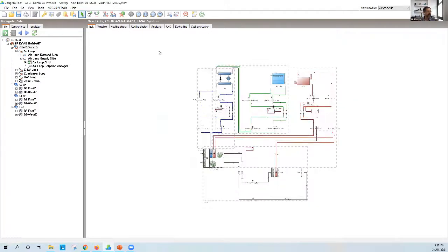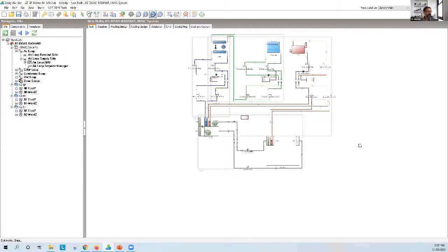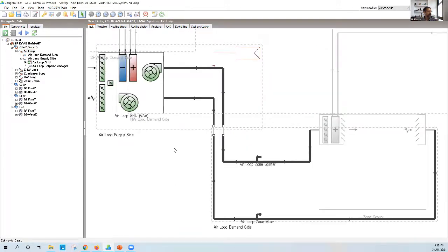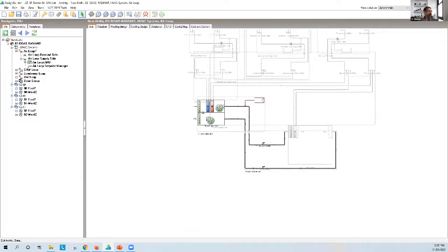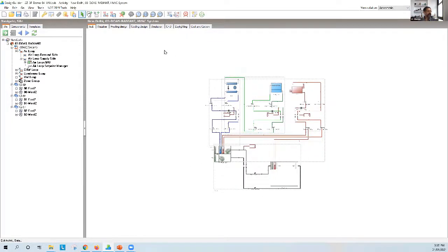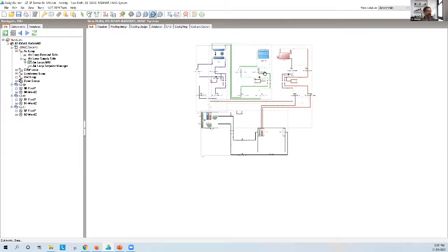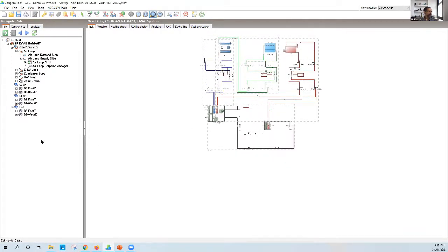Okay, so once I'm on the HVAC system, I can pull the whole system up and down. What I want to do is to clone the AHU and clone the system, sorry, the zone group. You remember what I said previously. You have a geometric representation and you have an HVAC representation for each group. Okay, so let me